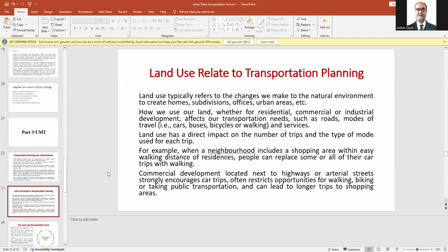And if this parking demand is not met, and usually it is not, what is happening is we have traffic chaos on those arterials, and people who have nothing to do with shopping are bound to pass through this congestion. Another is the location of educational institutes. That also creates a lot of demand, a lot of congestion. So when you are planning the city, we need to allocate places and ample space for these types of land use.